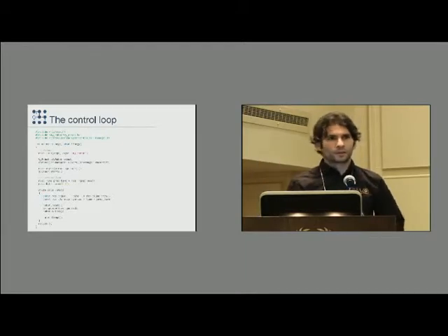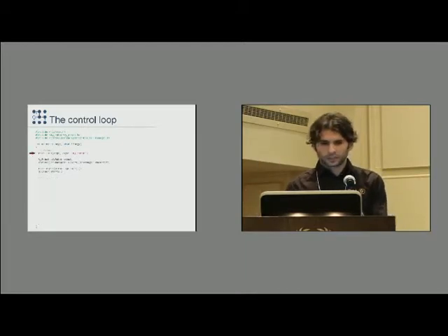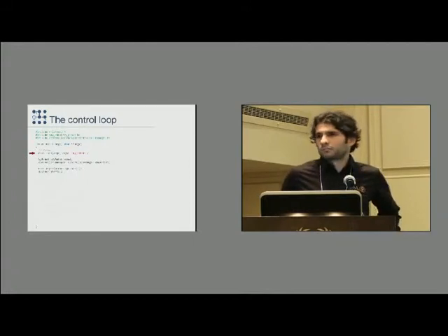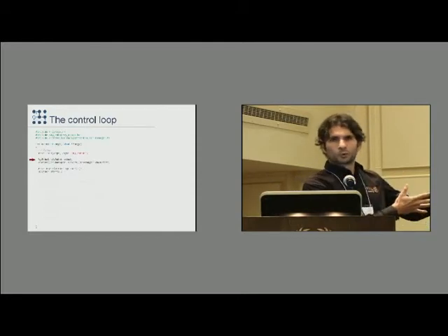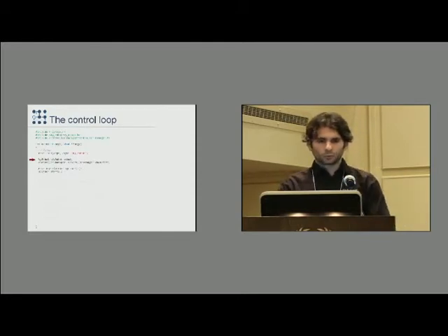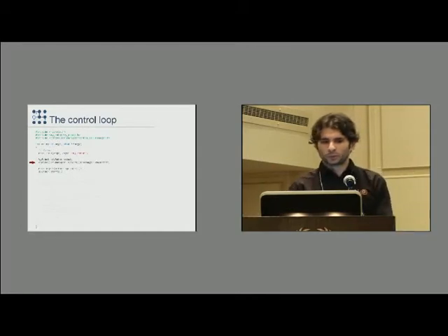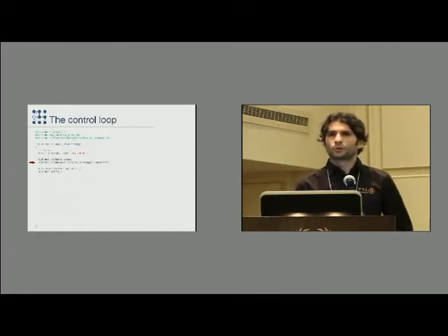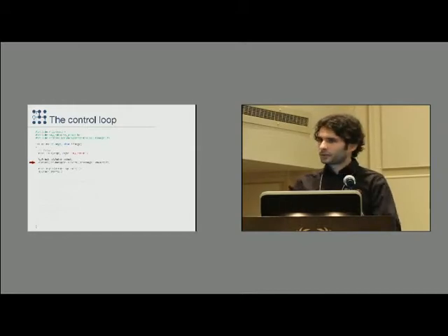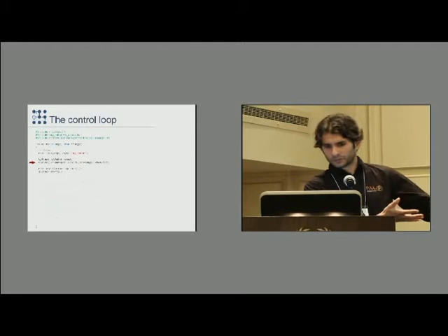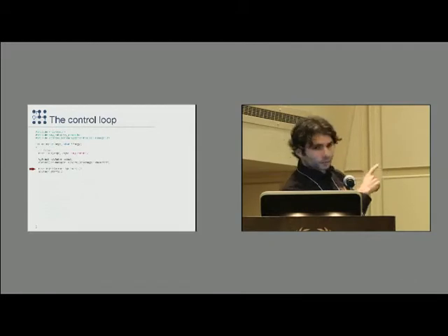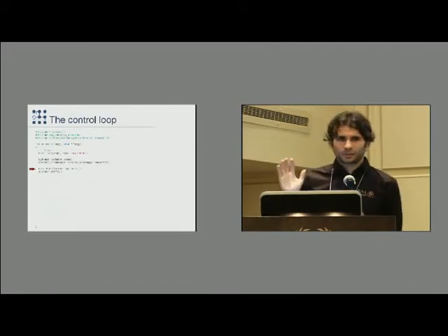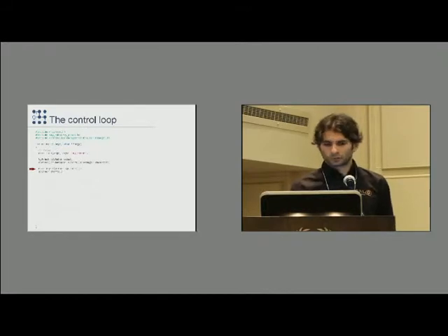So this is probably the only piece of code that we're going to be looking at. I'm going to step through a very, very simple robot setup. This is a main function, and the first thing you do is initialize your ROS node, and then create an instance of your robot. This is what we were talking about in the setting up your robot section. By this time, the robot knows about all of the resources that are available. Then you create an instance of the controller manager, and you say, controller manager, this is my robot, please handle those resources. And this is something we're going to come back to later on in this discussion. We set up a separate thread that is going to be responsible for servicing ROS callbacks.